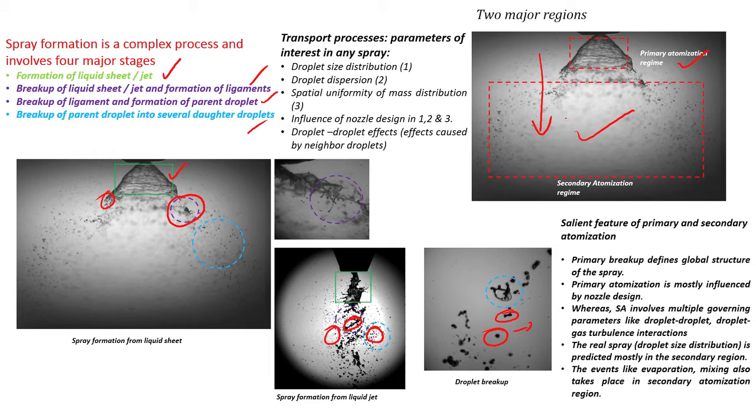Now, in between, these droplets start to interact with the flow, which has an effect on the droplet dispersion, how the droplets are spread, and how much the droplets evaporate also. All those things start to happen when you have a spray injected into a high velocity gas phase flow field usually.